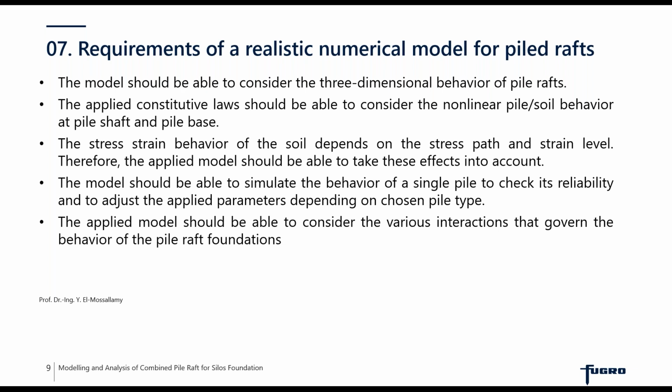So your model should be able to take those effects into account. And always, all these design assumptions should be justified using a pile load test. So whichever ground profile and pile-soil interaction you have modeled, you should always be able to check its reliability with the field pile load test.